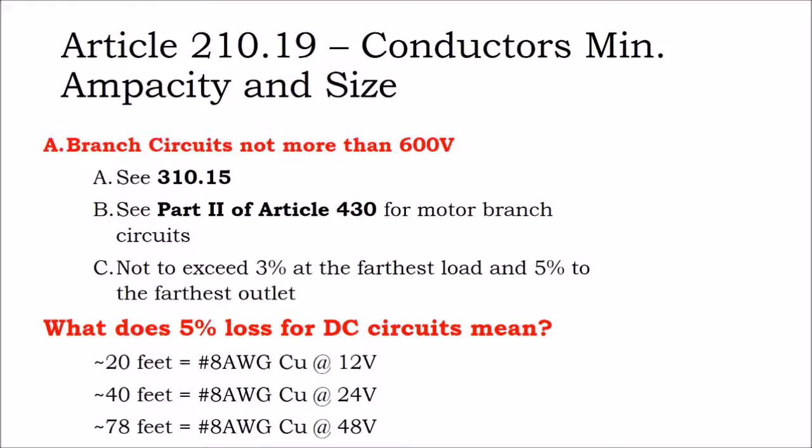But then if you want to do an off-grid house, and it's not a tiny house, it's not a yurt, but it's a home that most people would be familiar with, that you want to be comfortable living with, you wouldn't want to have that be a 48-volt battery bank where you're just running it off of DC only circuits. And it doesn't have anything to do with whether it's DC or AC really, although finding equipment might be hard if you're running at oddball DC circuits.